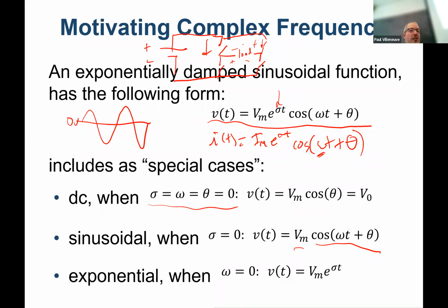It's a DC source. But how do you make a sine wave out of a DC source? You don't really change the ground reference. You just literally swap the leads, how your load is connected. If you talk about an H bridge, that's essentially what an H bridge does. It's constantly swapping leads back and forth.